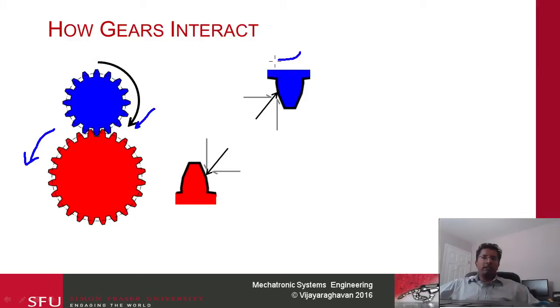In this gear, it rotates this way, and this gear's teeth want to move in this direction, right? So this gear is forcing it to move in this direction. This force opposes the direction of motion. This force moves along the direction of motion. So power is being removed here and then added here. So what you can do is think about what the actual values of the forces involved here are, right?